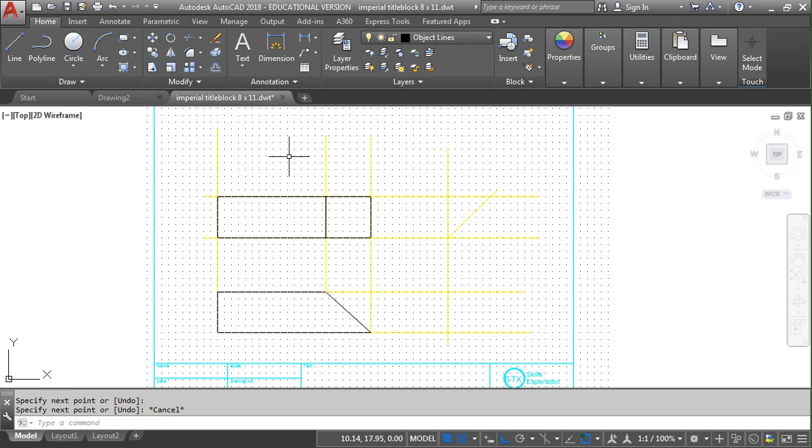Now to fill in this one down there, I'm going to go back to construction lines and go line. I can hit this intersection here, and it's just going to come down to the, whoops, Control Z. It's got to go past it again, right there. Then it automatically changes over to my object lines, and then I can do this. And there's my lines there.